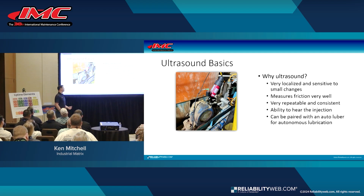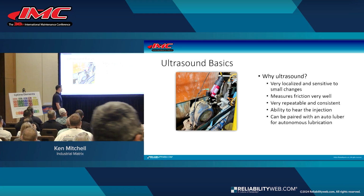Well, ultrasound is very localized, just due to the nature of the sensor. When I stick an ultrasound sensor on a pillow block, it doesn't really care about what's going on further down the machine. It's a very high frequency, usually in around 30, 40 kilohertz. And what that means is if I had an ultrasound sensor right here on my podium, if that was a machine down there banging around in that high frequency bandwidth, the sensor's not going to pick that up. It's really focused on what's in front of it. I like to say about a 1 foot radius. So we know exactly what's in front of us. We're kind of blind to anything else outside of that.